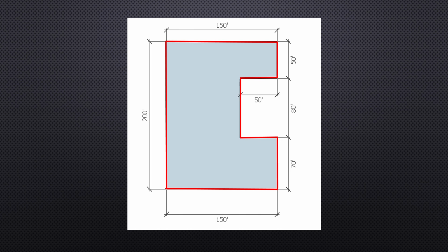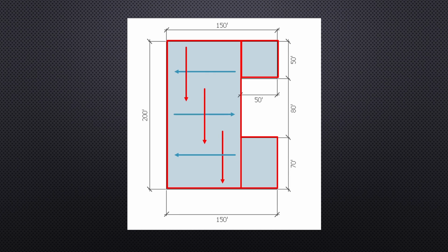Or if you are more conventional, then you may opt to lay out your sections like this. Of course, you can do it this way as well, especially if the little sections still allow you to use the 2-foot boundary rule. For the long section, your run layout may look something like this. At this point, other than gathering job-specific information for your report, you now should have a solid understanding of how to break a floor up into sections, calculate the amount of data that you need to gather, which is N-min, as well as lay out your runs.